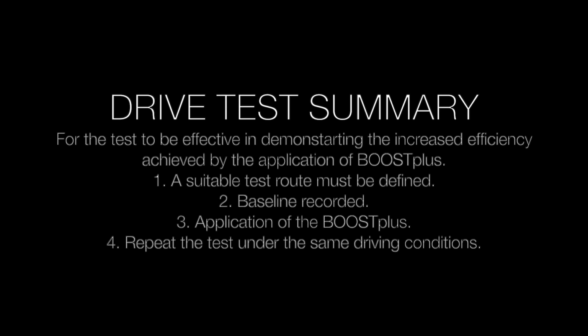So in summary, for the test to be effective in demonstrating the increased efficiency achieved by the application of BOOSTplus, the user has to define a suitable test route. We will then prepare the baseline recording using the Torquepro. We will then apply BOOSTplus to the fuel supply for a minimum of 7 days to achieve cleanup in the engine, and then we will repeat the test under the same kind of driving conditions. From this we can take the recordings from both drive tests and cross-analyze to see the fuel saving achieved.